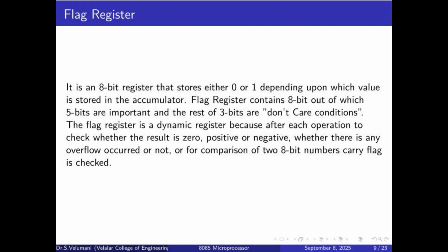Flag register. It is an 8-bit register that stores either 0 or 1, depending upon which value is stored in the accumulator. Flag register contains 8 bits, out of which 5 bits are important, and the rest of the 3 bits are don't care conditions. The flag register is a dynamic register because after each operation, we check whether the result is 0 or positive or negative,